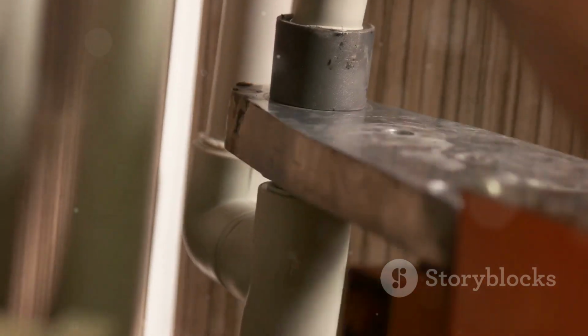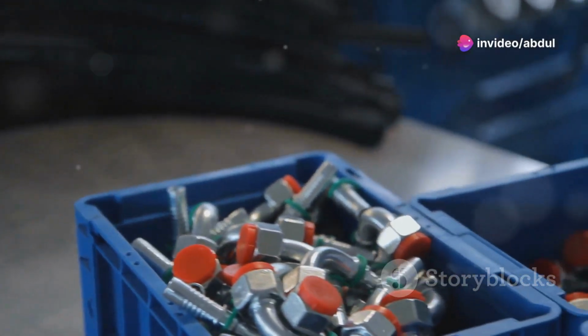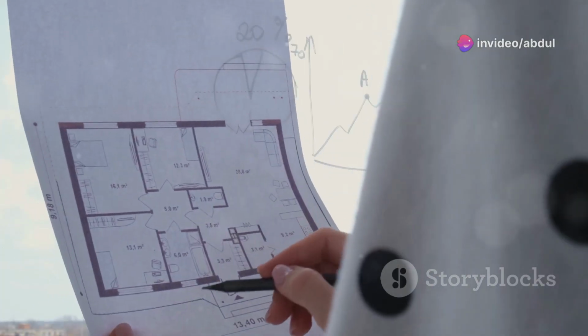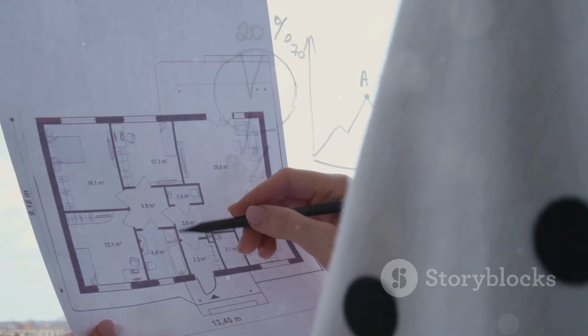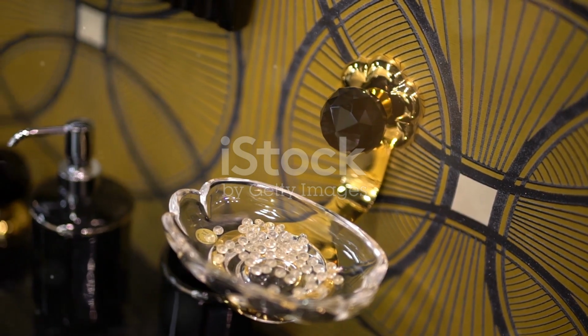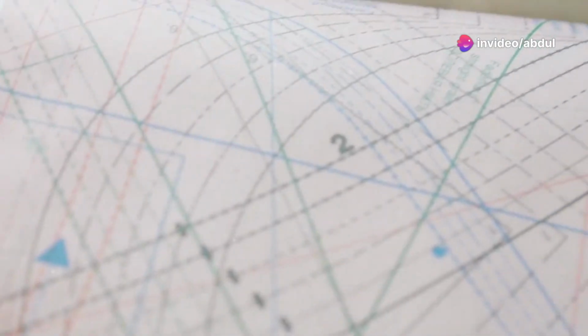You'll also need to indicate the diameter of the vent pipes, which varies depending on the fixtures they serve. Remember to consult local plumbing codes to determine the correct sizing and placement of vent lines. Building codes can be a bit of a headache, but they're there to ensure the safety and functionality of your plumbing system. Next up, we'll add dimensions to your drawing to make it crystal clear for anyone who reads it.